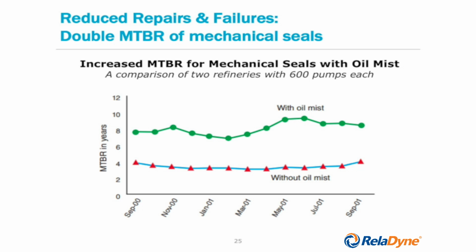But the question now is, why were mechanical seals affected here by oil mist? After all, the mechanical seal is not exposed to oil mist. That statement is, of course, correct. But going back to this slide, I'd like to remind you, as you listen in on this webinar, that it is very frequently the bearing that causes a consequential damage of the mechanical seal.